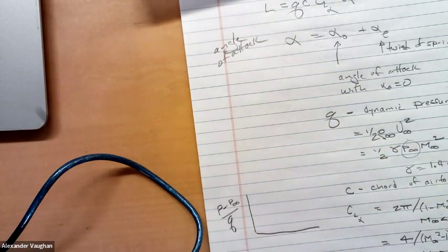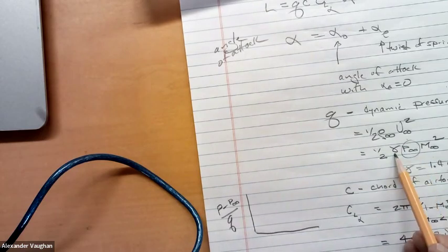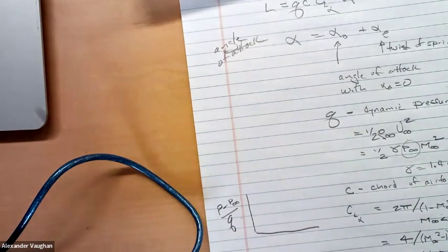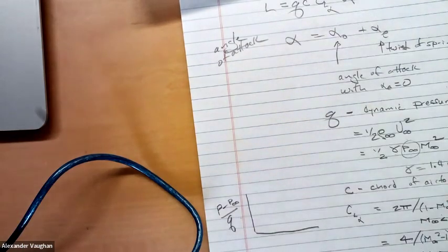It's density times velocity squared, or here you see gamma's a number, 1.4. This is a Mach number, which is non-dimensional. So Q has the same dimensions as pressure, right? So this is a non-dimensional number. And the aerodynamic theory says that's universal in the sense that if I plot this versus the chord, for example, for a fixed Mach number, I'll always get the same answer. Okay. And for a small enough angle of attack, everything will be proportional to the angle of attack.